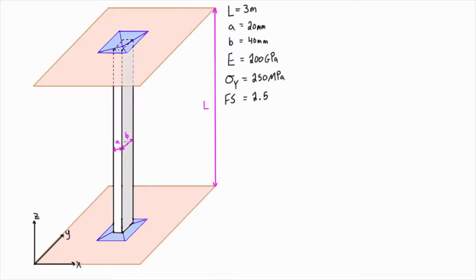So looking at this, we have a 3-dimensional column here. And we're talking about this as pinned joints, a pin on each end. So we'll basically treat these as ball and socket joints, so this pin is like a pin in 360 degrees. But because this rectangular cross section has 2 distinct ways it can buckle, basically in the YZ plane, as we're looking, it can buckle from left to right or right to left, like that way. Or it can also buckle in the XZ plane, so basically going into the page that way or out of the page that way.